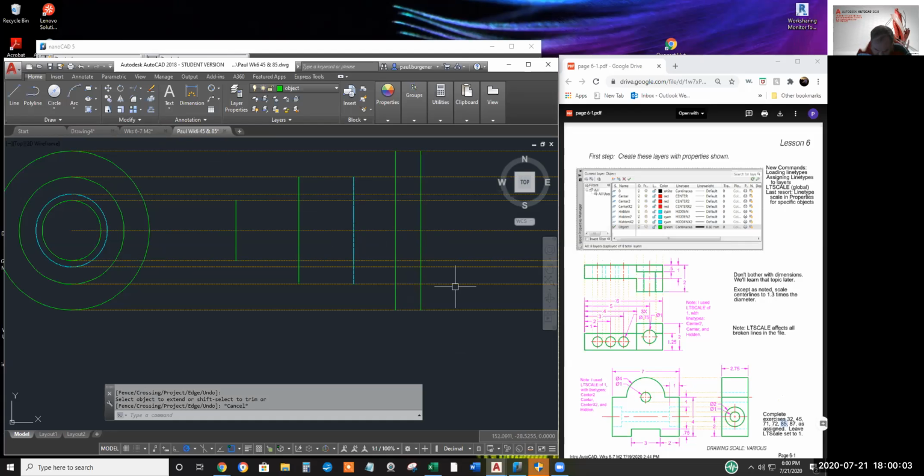Top of the keyway is only 5. From here, we'll offset this guy 11 to the right. It should be right there. Offset, enter, 11. What happened? I was hitting escape instead of 1-1. There.